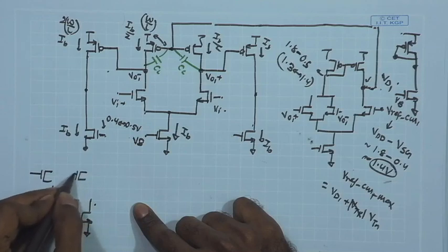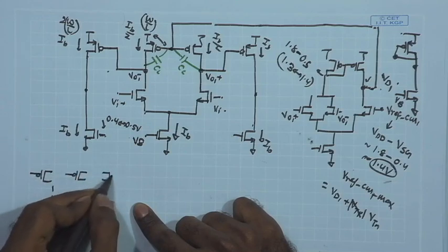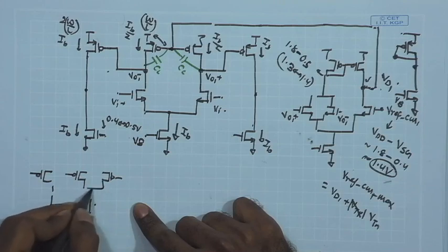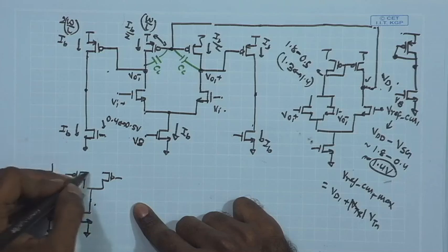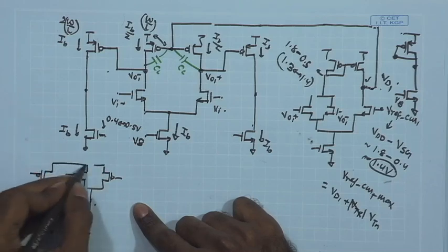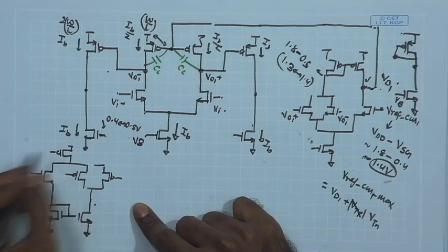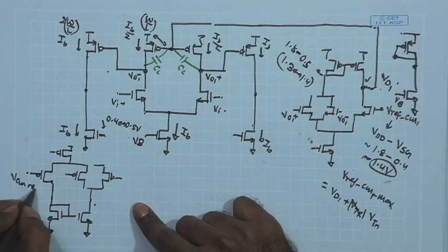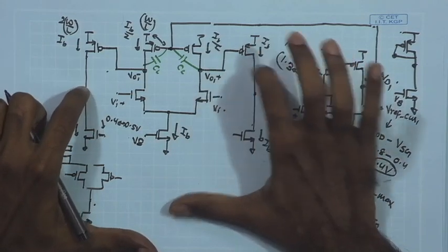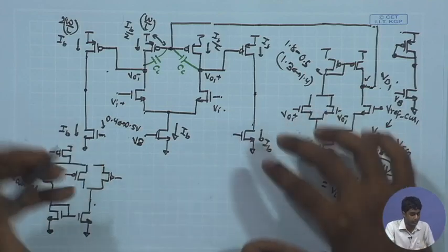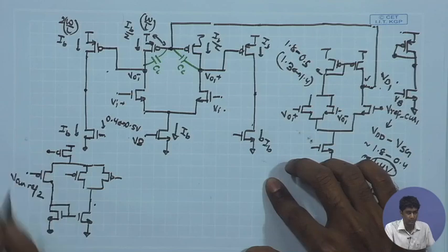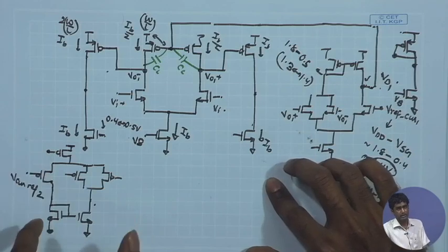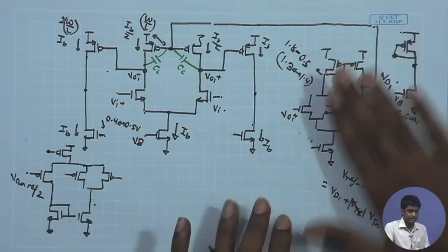This is the reference one, and this has to go on the other side. I'll do that, and you have the PMOS current source. So here I can put my VCM Ref 2, which is the output common mode reference point. Now, what should be the output common mode reference point? This is anyway a DC bias, so from the AC point of view, I can put it at AC ground. So this is again my differential amplifier, the same error amplifier topology.